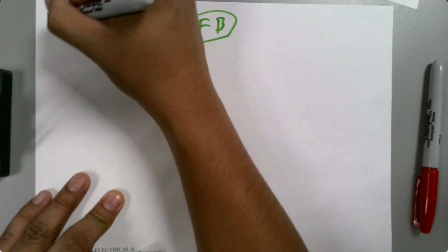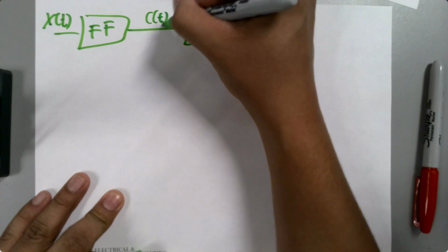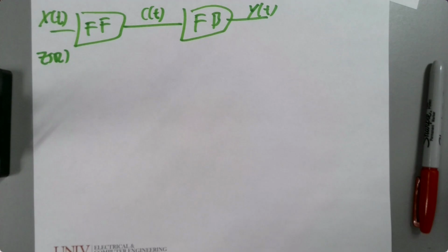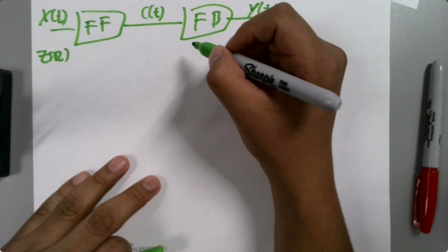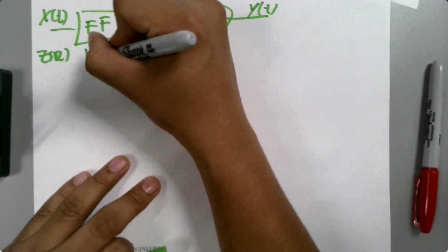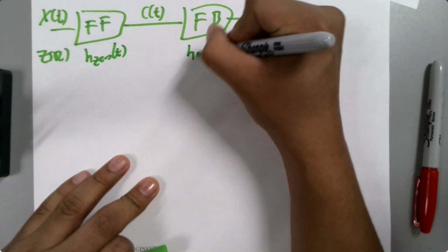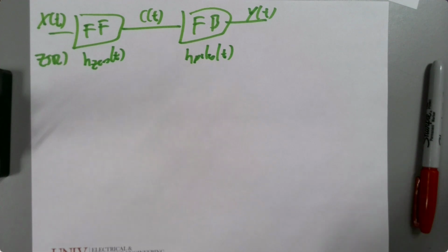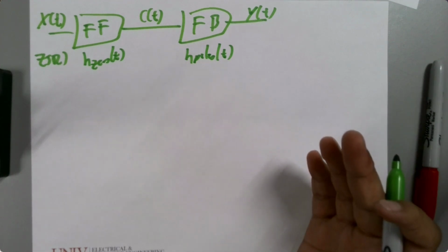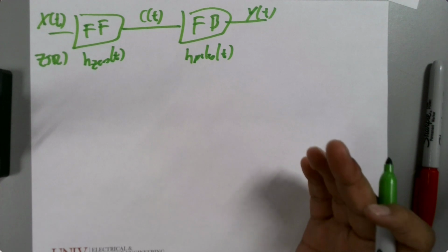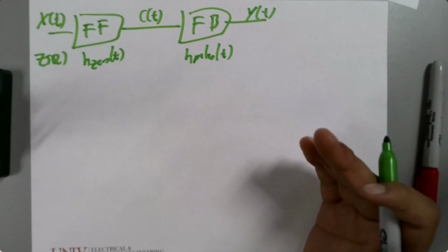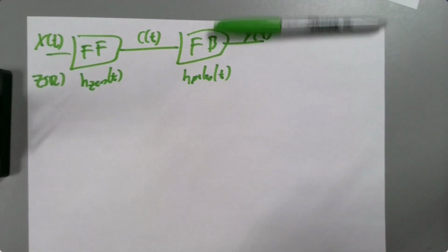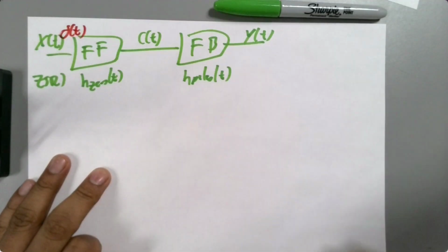So now you just built two individual parts for the ZSR, okay? So now, if I gave you H of zeros, H of poles, and I say find the ZSR, or the zero state response, right? What is a zero state response? It's an impulse response. What do you do with an impulse response? Kick this box. That's it.